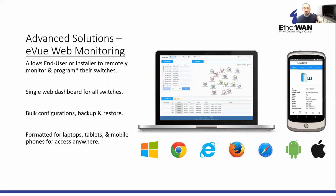So it's going to actively alert me when one of my switches drops off or when I'm having PoE issues. Maybe it's going to let me know that, hey, I'm having a derating issue because I've had a number of cameras dropped out and I'm getting a PoE alarm on one of my switches. So it can give you some really handy information to be proactive about managing your network. Again, a big network, critical infrastructure, mass transit, public works, things like that need to stay running. This is a way to keep eyes on a very large network, or be proactive even on a small one.